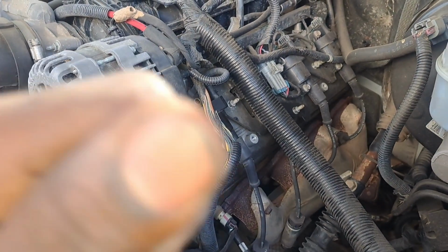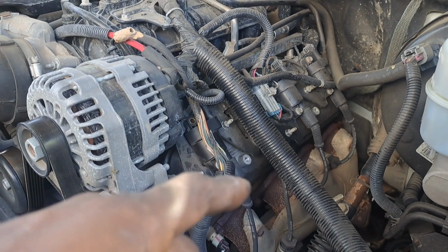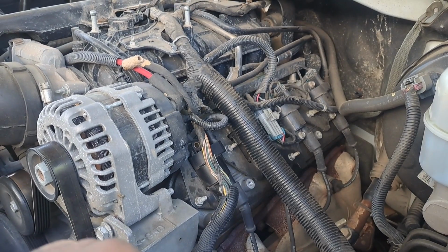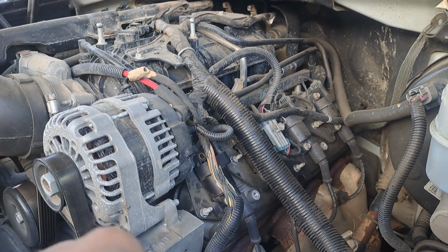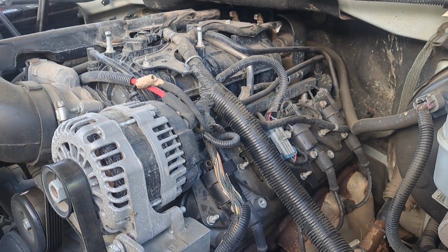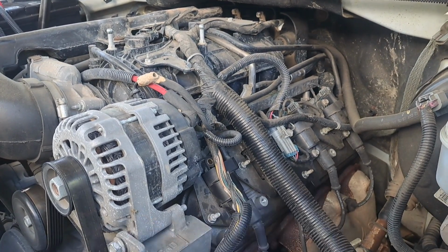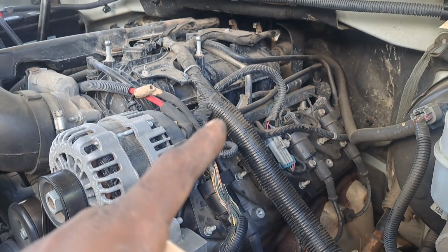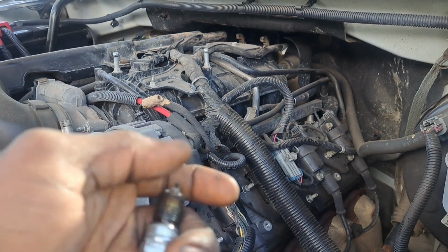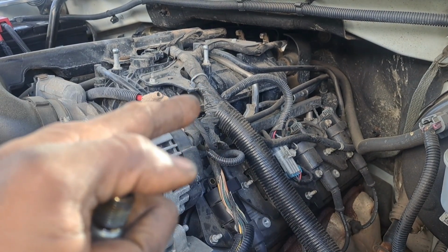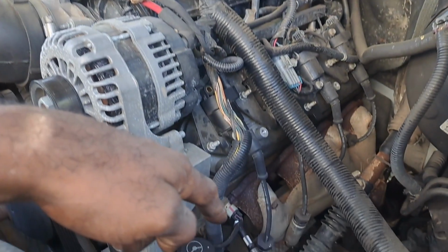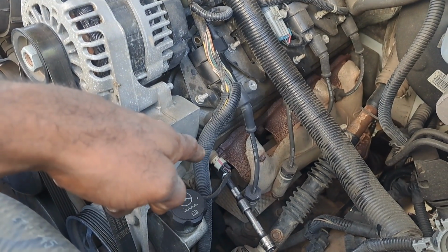So it's the next day after doing some investigating on what could cause this issue from Identifix. I didn't have any specific ranges for this particular code, so naturally I'm like, all right, well, let me just bring up the maintenance on it. I was going to do an induction service for the fuel system because most people on Identifix had that problem, but I'm like, normally injectors don't cause that because our fuel trims aren't extreme.